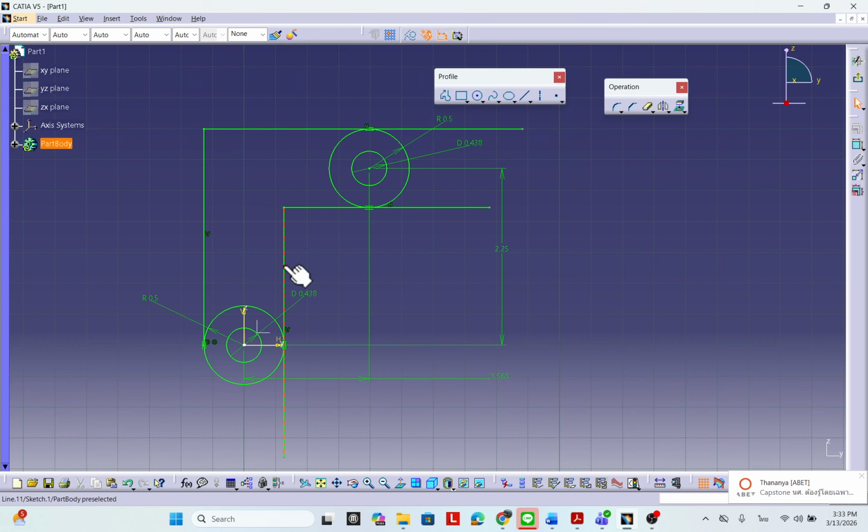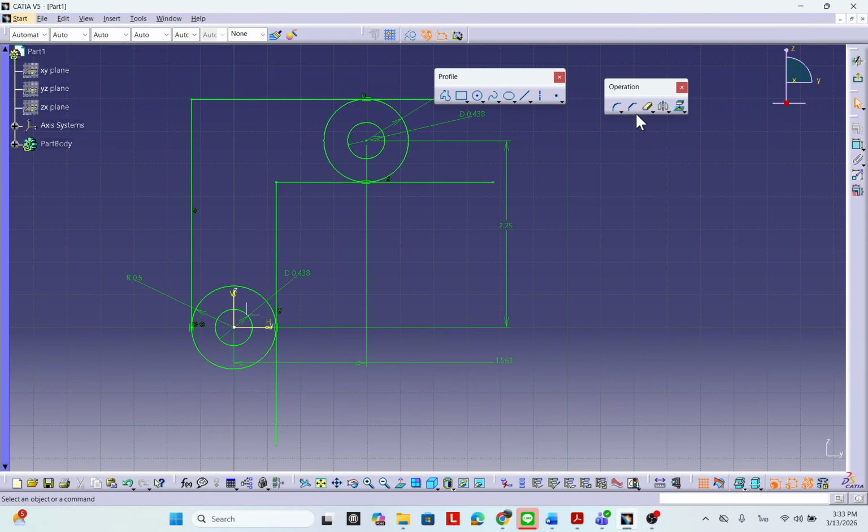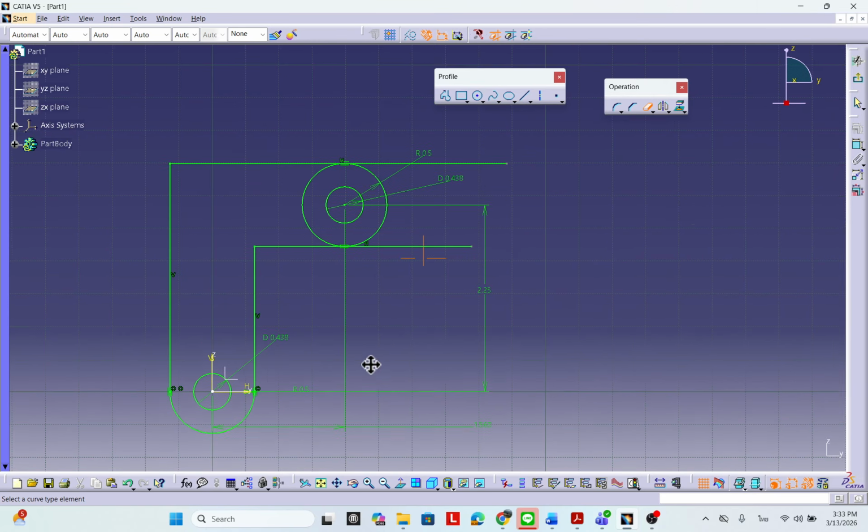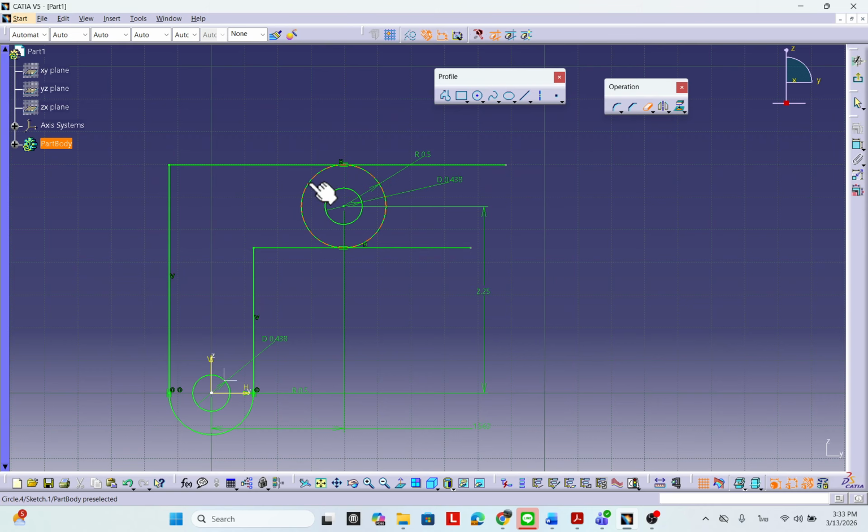And this one comes back to green again because you drag out and drag in again, touching this curve, and the tangent is created for you with automatic constraint. I just double click on the delete, and done.